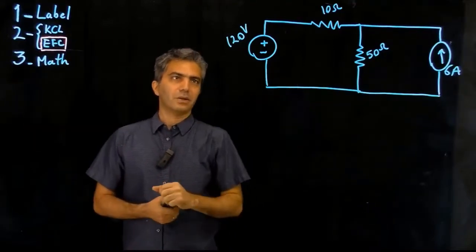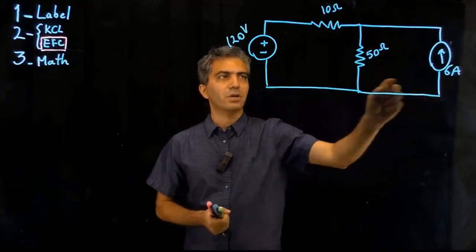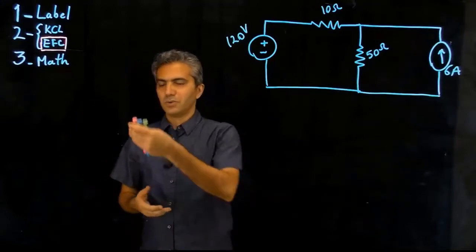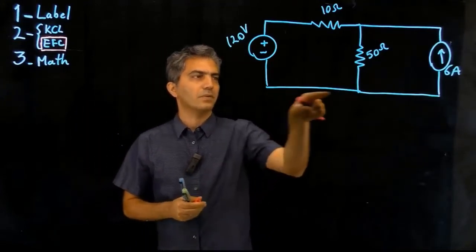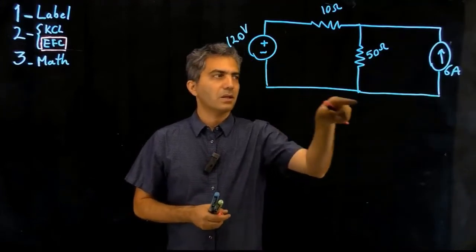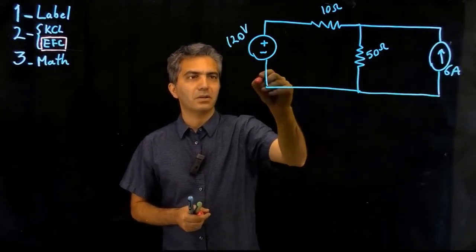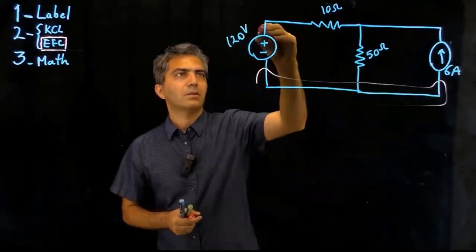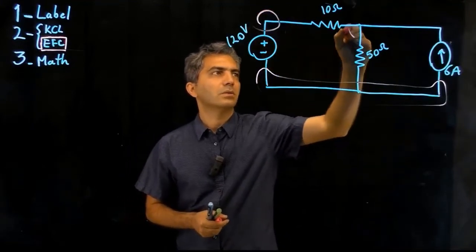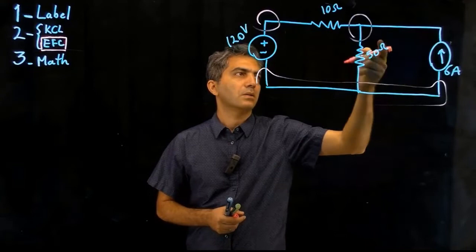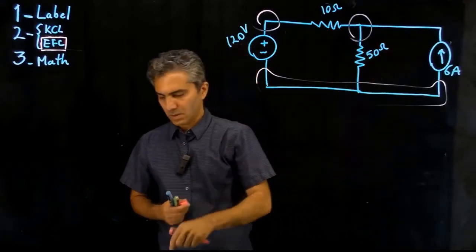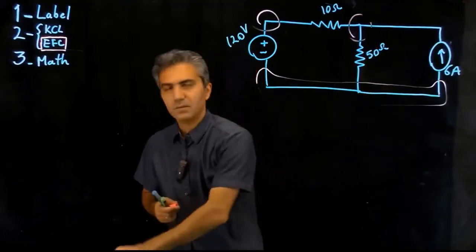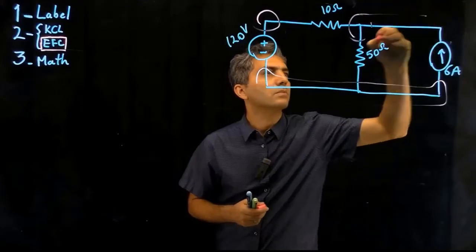We're looking at this circuit. There are two sources, one voltage source, one current source, and two resistors, so a total of 4 components. Let's identify nodes first. So ends of the components are nodes, and in this case the 3 ends on this end, they're connected to each other, so this is one node. There's another node here, there's another node here, and this is actually all one node, so we can extend that. So this is all one node.